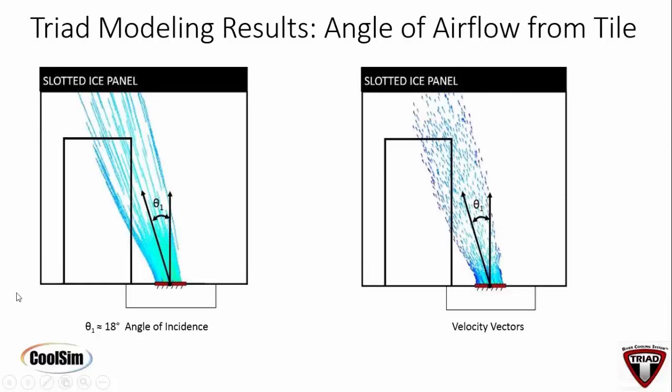Flow starts over here on the left, coming across under the floor out the other side. So the effect of the fin there is to catch that air and redirect it back towards it. It actually does a bit of a bounce off it and redirects it back towards the cabinet. Now, this assumes air only comes in one direction, to the left. That's the only place we measured it, was left to right.